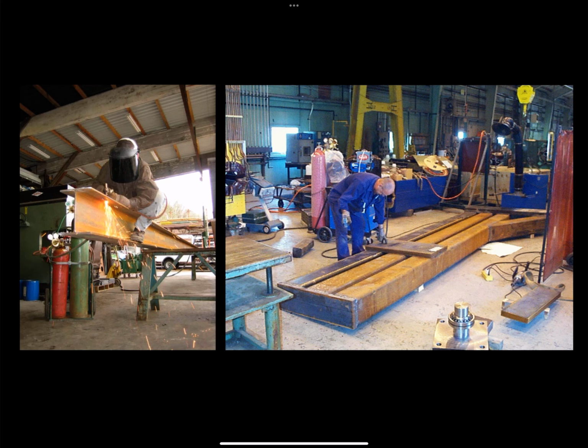The shop drawings then come back to the design team, the architect and the structural engineer, who have to review them and approve them for fabrication. And so, as an architect, you can either approve the drawings for fabrication or approve them provided the changes that are noted or redlined on the drawings are incorporated, or if substantial changes are required, you can refuse to approve the drawings and require them to be amended and resubmitted for approval.